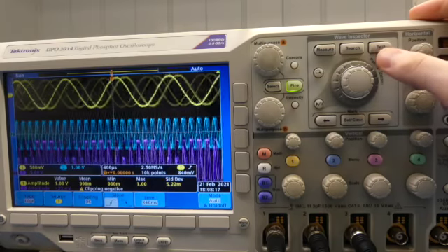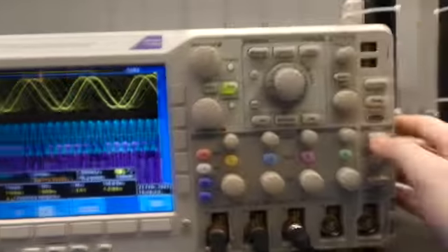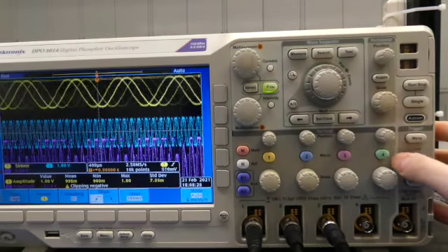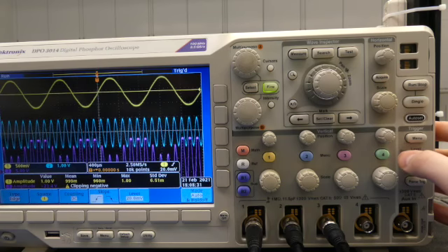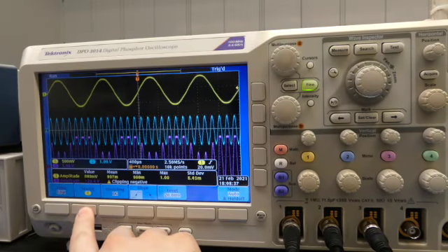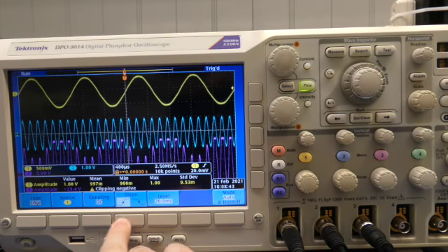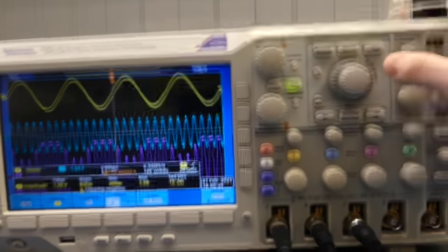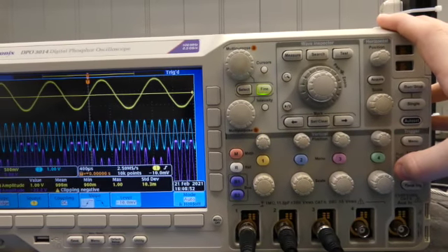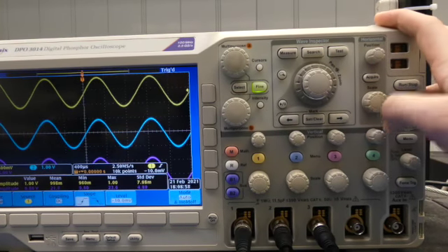Okay, so this is kind of the most simple way I can put it based on how I know how this works. If the trigger isn't automatically set by auto set to somewhere where it should be, you can turn the knob until this starts to get in line with the waveform that you're looking at. In this case, where I have it set to input number 1, make sure that it's set to type edge, and it's DC coupled. And everything else you shouldn't have to mess with. And again, just move this line, the trigger line, until it's at a point where everything is not moving. Let's reset my AC waveforms back to where they should be.